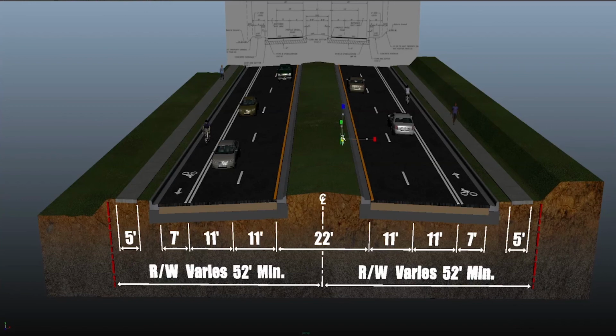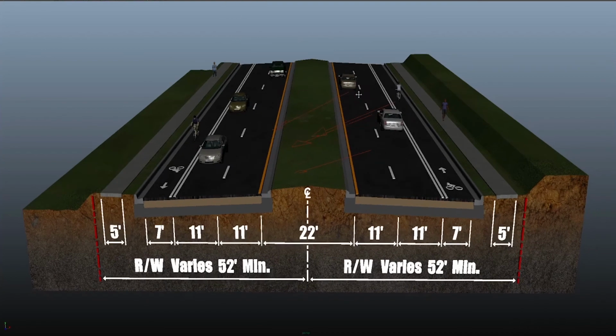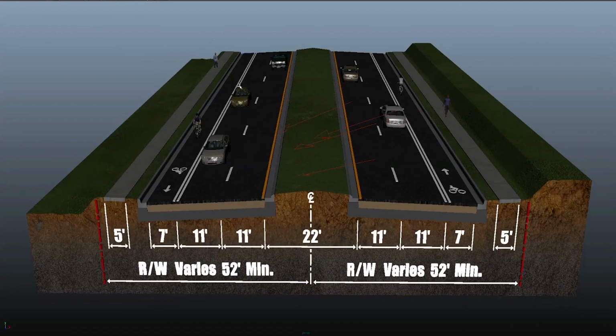We adjust our sunlight here. This is our sun. This is a directional light. We don't want it straight down, it'll blow out the image. So I like to put it at an angle, maybe about 45 degrees that way, something like that. Let's go ahead and hide the plans, get that out of the way so we can see what this looks like. Let's go ahead and render.